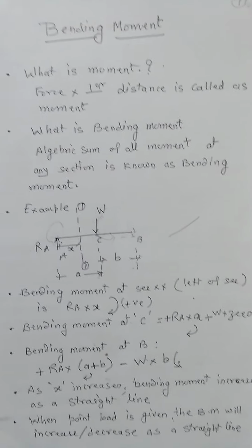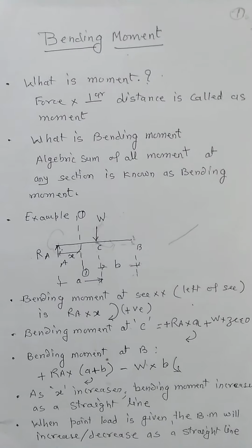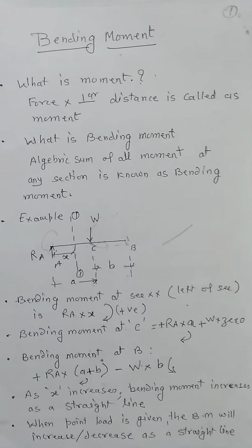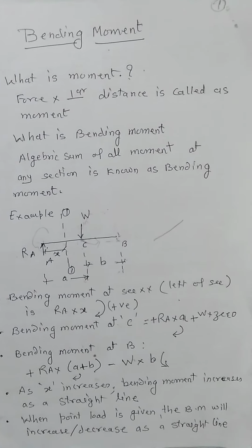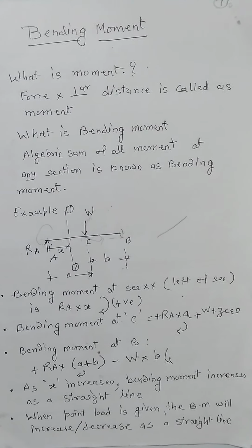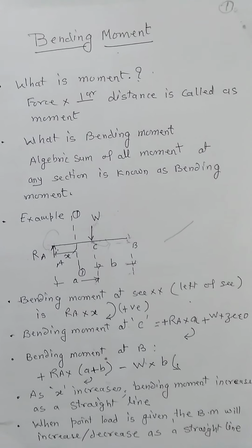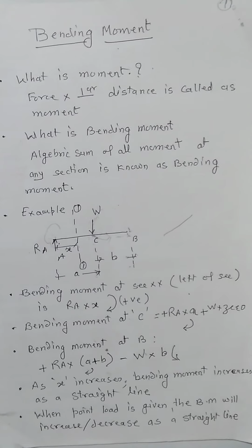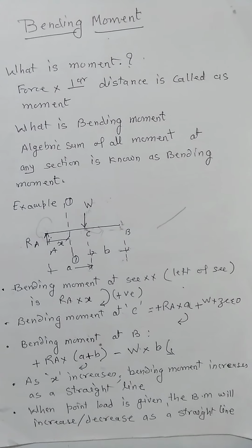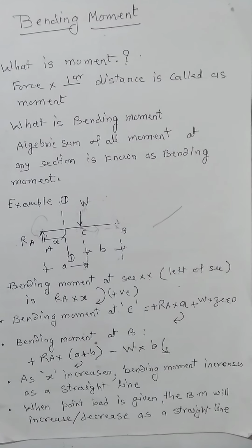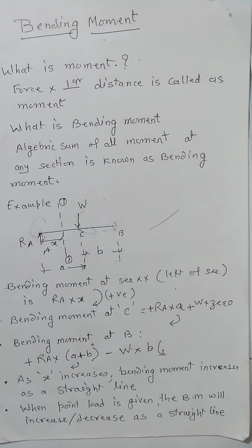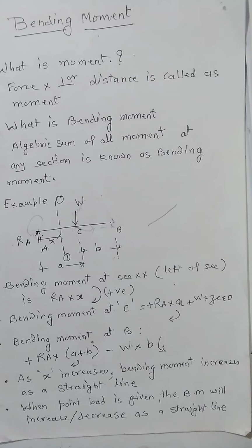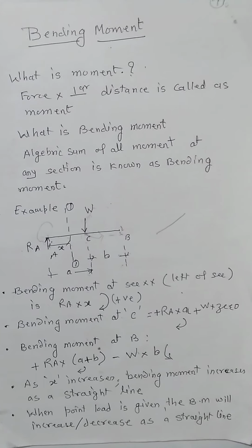In this lecture, we are dealing with bending moment. But what is bending moment? Before that, we start with what is moment. Force into perpendicular distance we call as moment. Then what is bending moment? That is the algebraic sum of all the moments taken at any section is known as the bending moment.